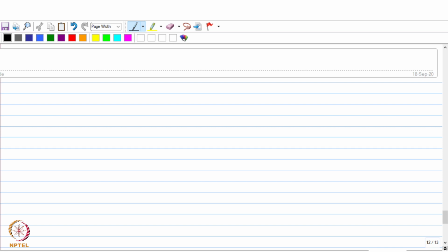And if you keep on heating the material or keep on holding it at a particular temperature for a longer duration, then due to this driving force, there will be a tendency for the grains to grow further. Okay, so if you let this happen, in fact, there could be a situation where the grains can grow abnormally, okay, beyond a particular time.